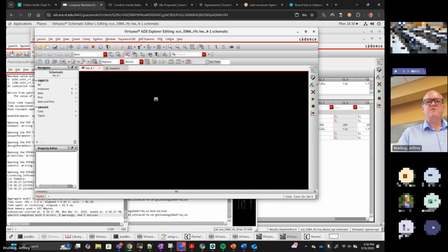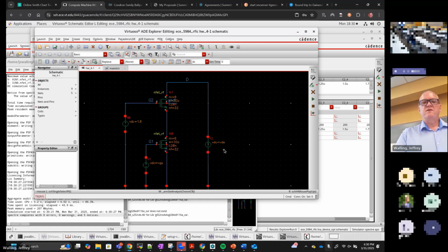Oh yeah, a couple things while we're looking here. You can try and save the drain currents to the output, but Cadence sometimes has fun with these. For some reason, sometimes it just doesn't like to plot them. It depends upon the data format that it saves them in. It can be tricky, but Cadence will always provide you the current flowing through the supply.